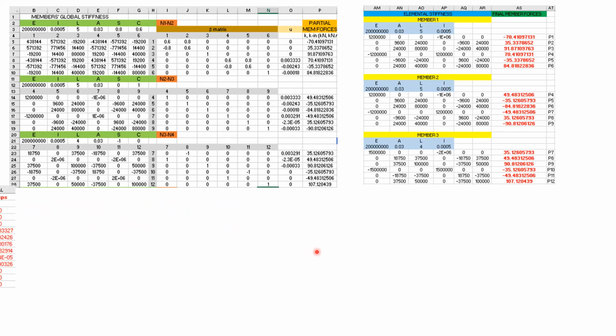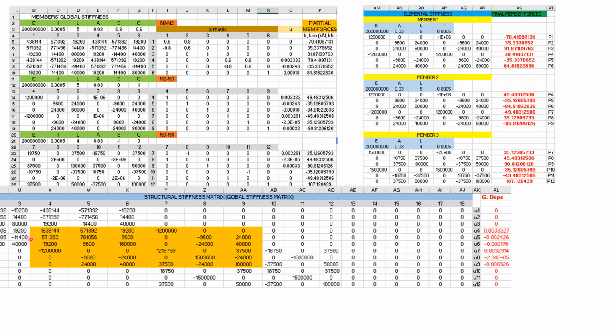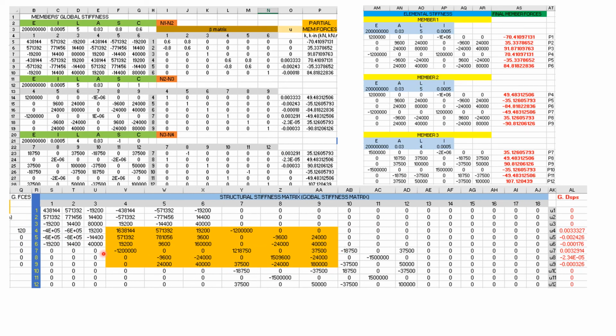Then the global stiffness matrix is this, and look at the load and the shaded part, which is 6 by 6. That is important to be inverted and multiplied by this force matrix, and the only value is 120. The rest will be 0, because remember that the load is horizontal, acting at a joint, so it cannot produce moment, shear, or whatever.